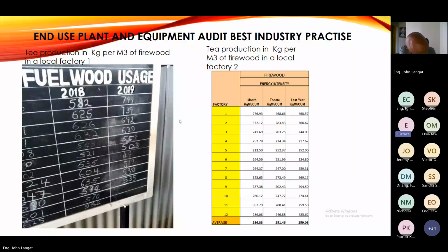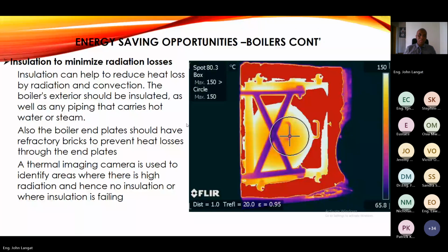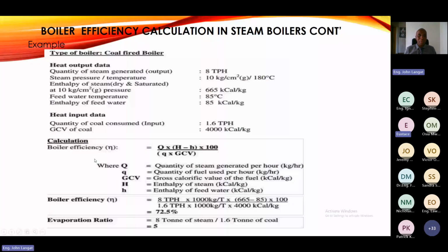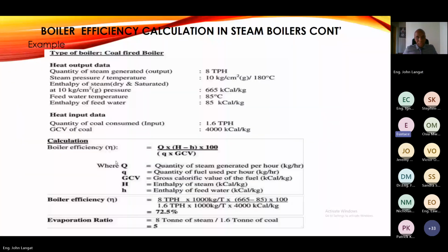If you look, Engineer Lagat, can you go to the place where you have shown the equation for the steam fuel efficiency? This one. The reason I am stressing this for auditors is that, after you have assessed the boiler steam system in parts, the condensate, the steam traps, the combustion efficiency and so on, the boiler steam fuel efficiency is the last resort to show the performance of the whole boiler steam system.